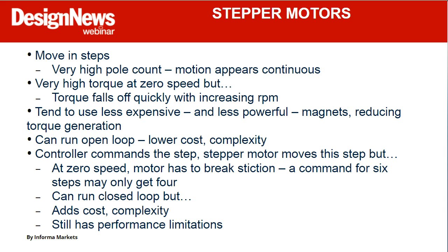Not quite, again, that cut and dried because you can kind of think of a stepper motor as a mass on a spring type of model. So if you are at 0 speed, then you command a step, the motor's got to break that friction. So you command 5 steps, you might get 4 steps, you might get 6 steps.